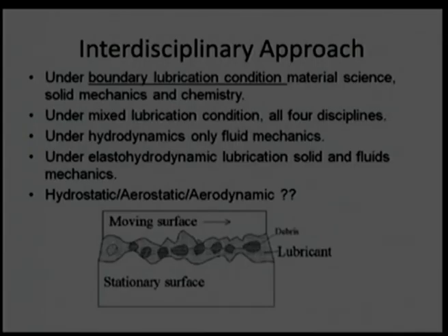Another interesting fact which I want to highlight is that maybe sometime you can keep using only hydrodynamic lubrication mechanism, assuming your 2 surfaces are always separated, and we are accounting at the initial level, or the start level and the end level. We are pumping liquid, we are levitating 2 surfaces or one surface relative to the other surface, and we are always trying to keep the mechanism or contact pair under hydrodynamic lubrication, but it is not a general case.